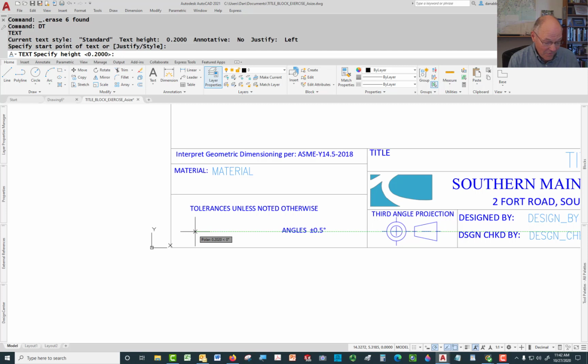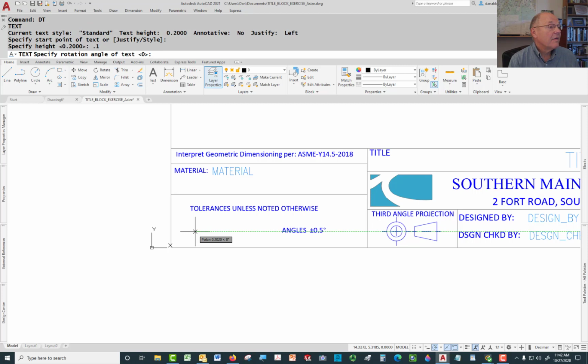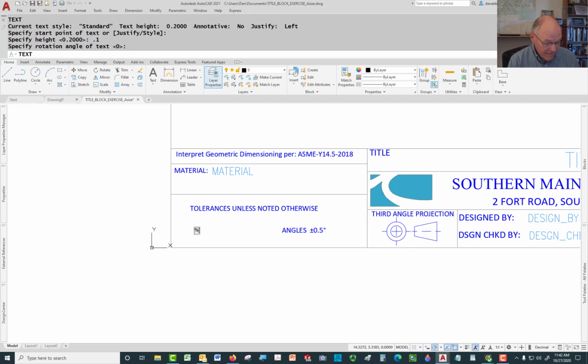And in AutoCAD, I can do that with percent P. Oh, gotta do the height. 0.1 angle. All right, percent P is the plus or minus symbol. 0.0, probably 1/100th of a millimeter. So that is going to be, oh, but I am in a metric drawing here.